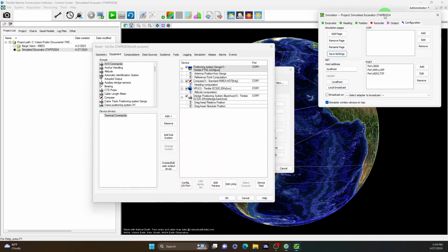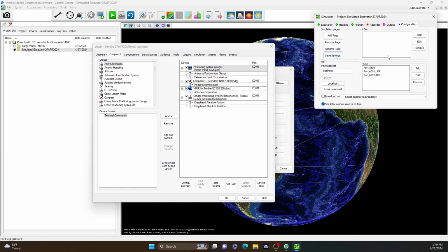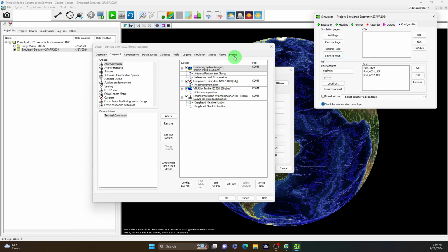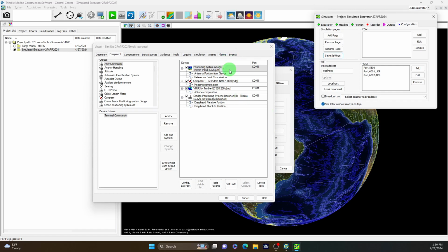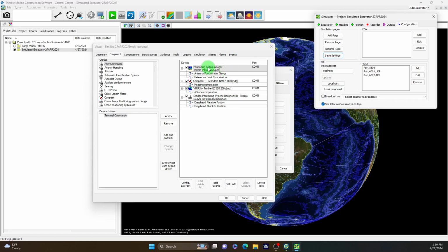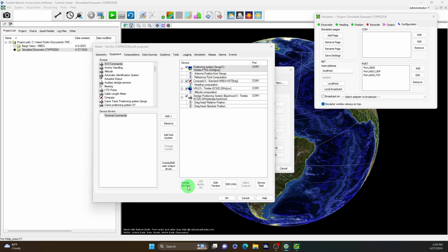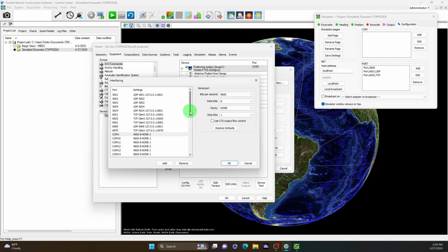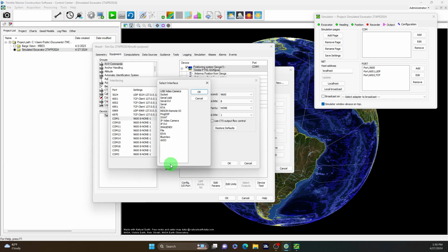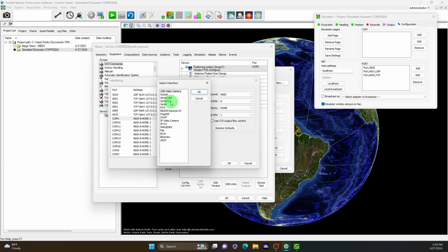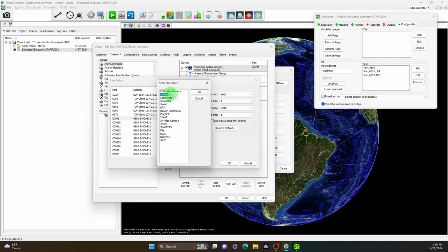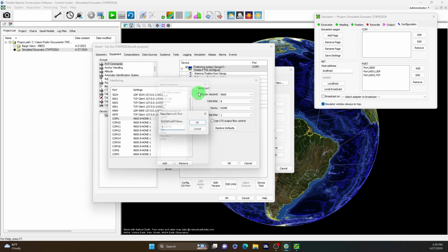And now we can set up our I/O ports here to match our simulator ports. So if we go to positioning system GEOGS, we'll configure our I/O port, and we will need to add one. Because we are using the simulator, everything is going to be on a socket, meaning network, Ethernet, whatnot. So we'll hit OK.